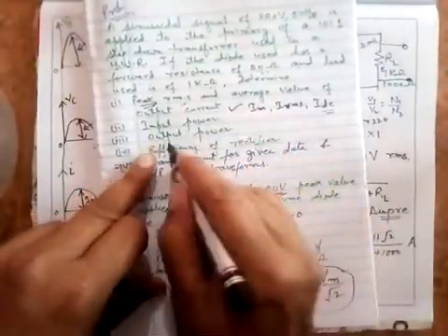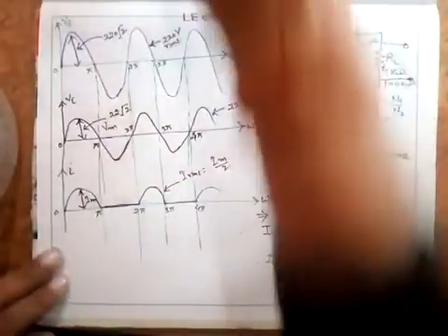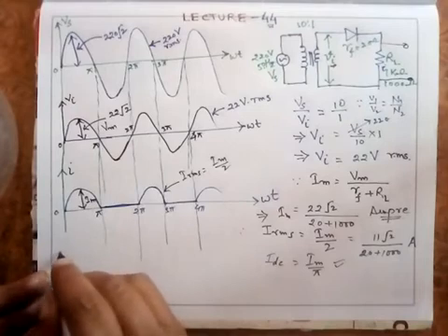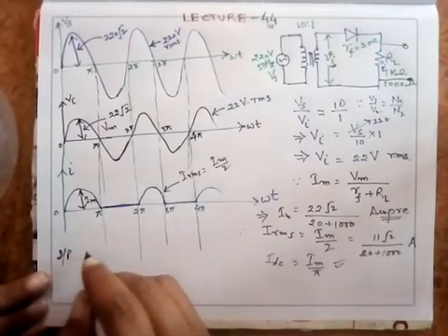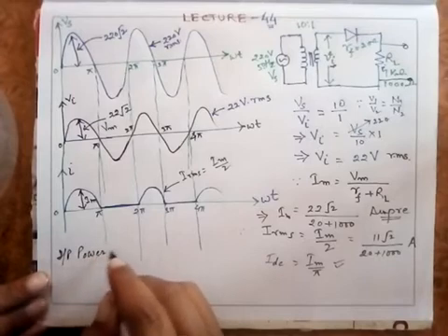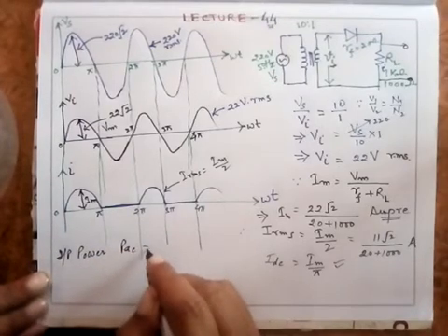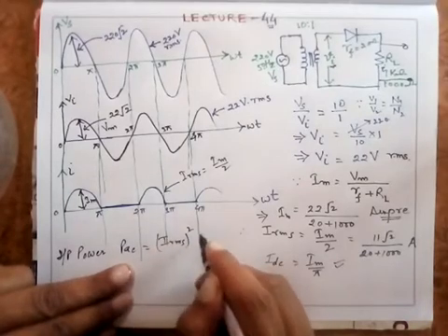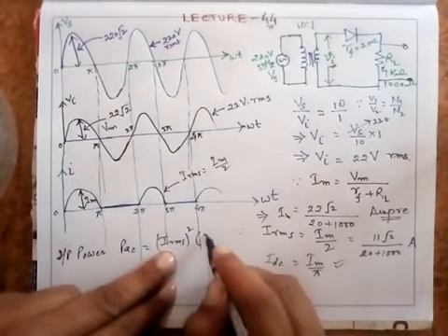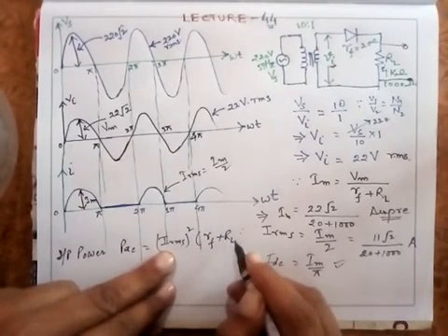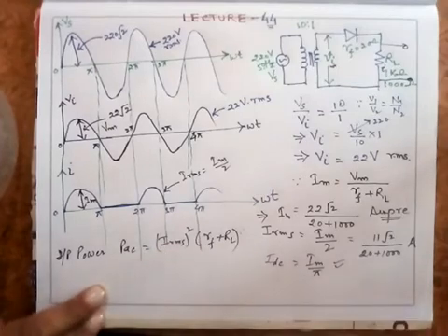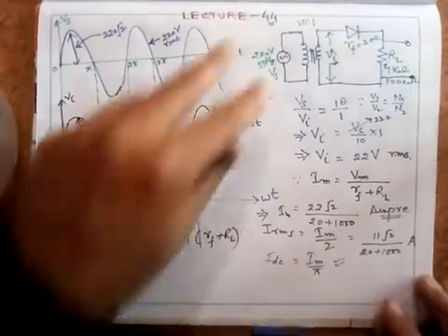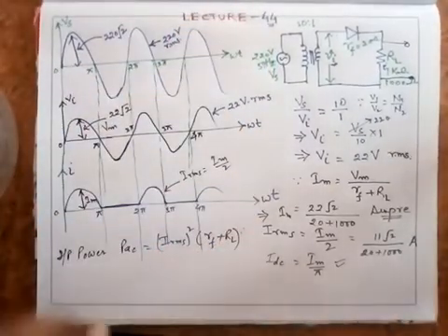is the input power and the output power. Input power will be AC. The input power which is applied here is of course AC. So PAC, input power, I'm writing here as IP as input power, that is PAC. Of course it will be IRMS whole square into RF plus RL. I have done this previously also with you. You simply substitute the value of IRMS, that is IRMS is Im by 2. We have done this.